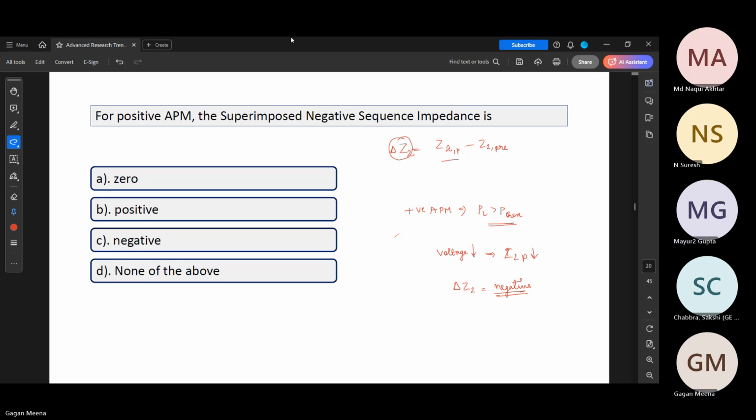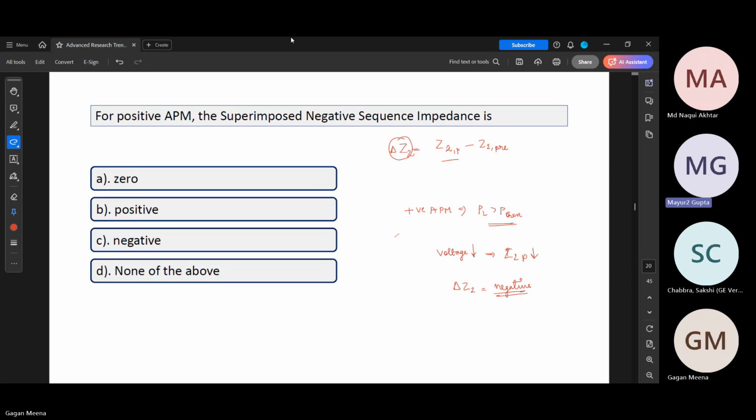Now consider we are complicated. If you consider an ideal system on a single bus and neglect the transmission losses and I squared losses and all those things, in that case, on a bus, if the frequency drops, I'll have to inject more active power to bring it back and hold the frequency. Correct.